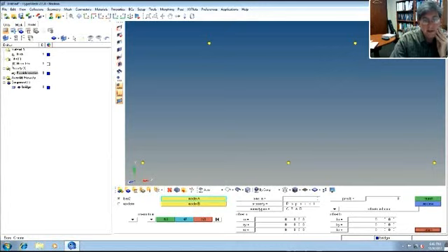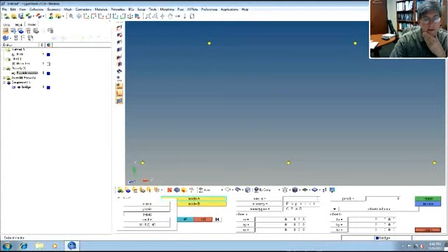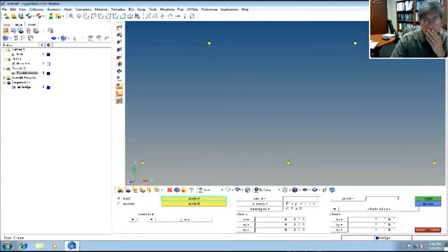Now in this case, all our elements are going to be in this plane. So if I pick an up arrow, if I pick the y-axis as my orientation vector, that'll definitely get those. It should also get all the other ones in this plane. So I'm going to take this orientation vector and make it to be a y-axis, okay? So now I should be good to go.